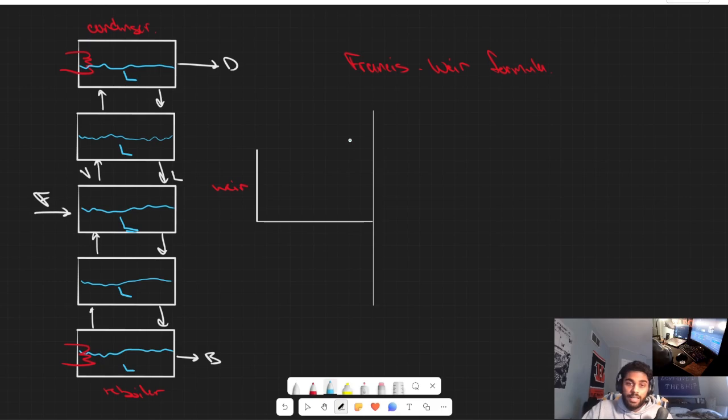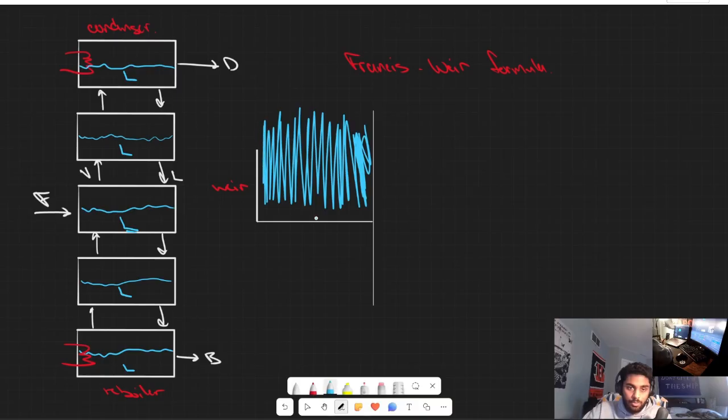What ends up happening is that as you collect liquid as it flows down from your condenser, I'm going to just draw an arbitrary amount through here. Of course, you're going to have some vapor that'll bubble in through the bottom of your tray. That'll be from the stage below. But what I am looking at is this amount of liquid that is no longer contained by the weir and thus is prone to overflowing and going down into the next tray. This is what we will define as the molar holdup.